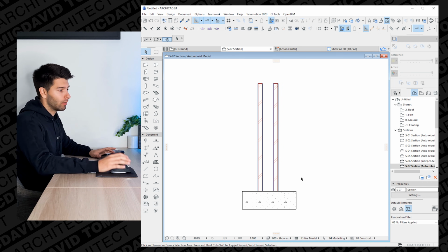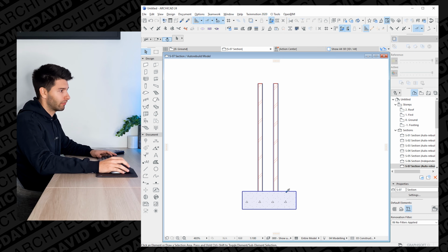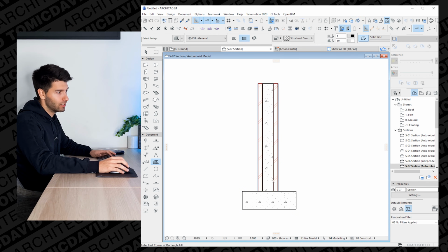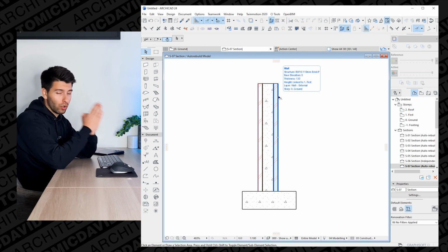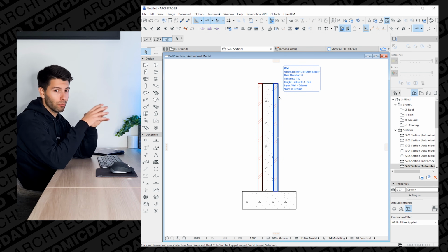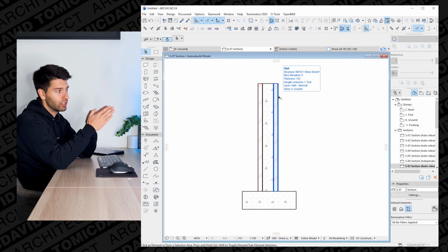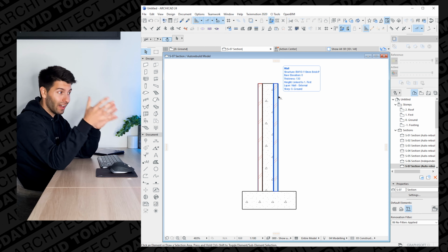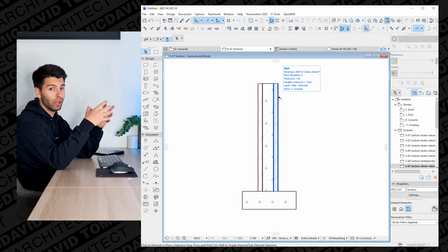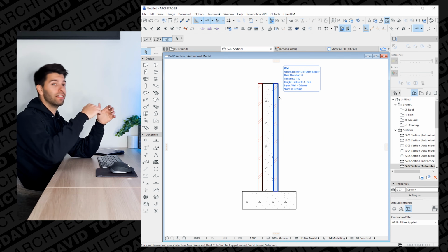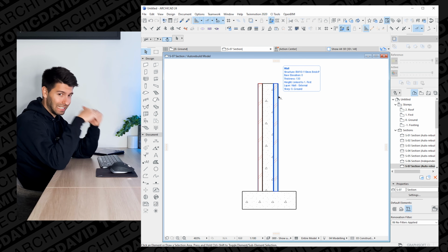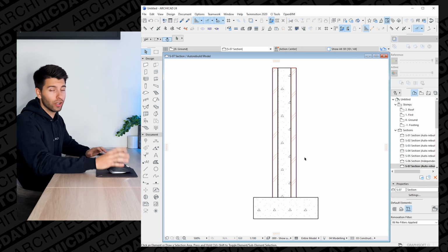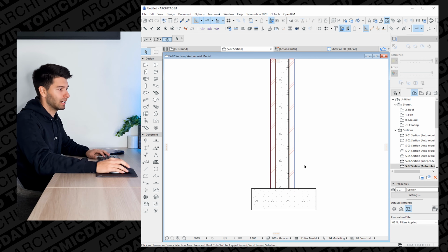Now, unlike that exterior brick wall that we did, this is slightly different. We are actually going to have approximately 300 millimeters right down the center of concrete filled cavity brickwork. So we'll have our traditional 110 millimeter brick on the outside, 110 millimeter brick on the other side, and then once that wall has been built and erected, they will pour the concrete directly inside of that cavity. Now, altogether, that would work quite well, but it would still be very unstable.